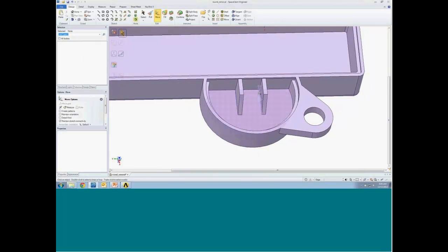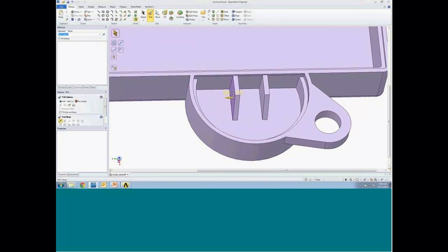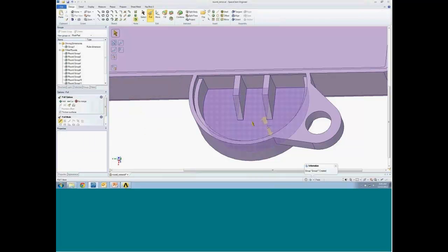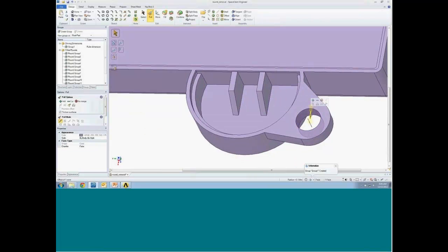Again, this is a dumb solid, so two completely separate faces, two completely separate ribs, but I for sure can tie those together if I want to and say, well, I want the width right now to be 50 thousandths. Let's change it to 60 so you can see them both changing. But I want to add a parameter now, because in a moment I'm going to send this model over to Workbench and try to optimize it.